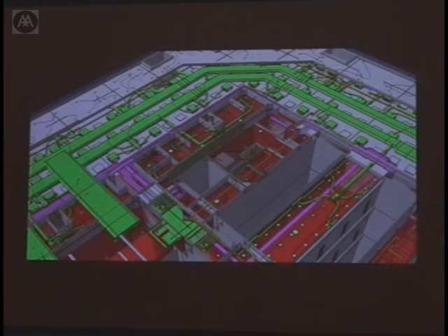And the thing gets more complex and even more useful when you start talking about project coordination. For those of you who have been in practice and have had to coordinate projects, you know that the mechanical engineer will do what's called a CSD, a combined systems drawing. The combined systems drawings look at integrating all the different mechanical systems: ventilation, plumbing, fire safety, electrical, and so on. And those never work, right? In most cases, they never really work, and you sort of kludge them on site in some form. As I said before, in a particularly complex project, it just won't work. In this one, it's just a lot of wastage, and that's the money that the client is trying to save.